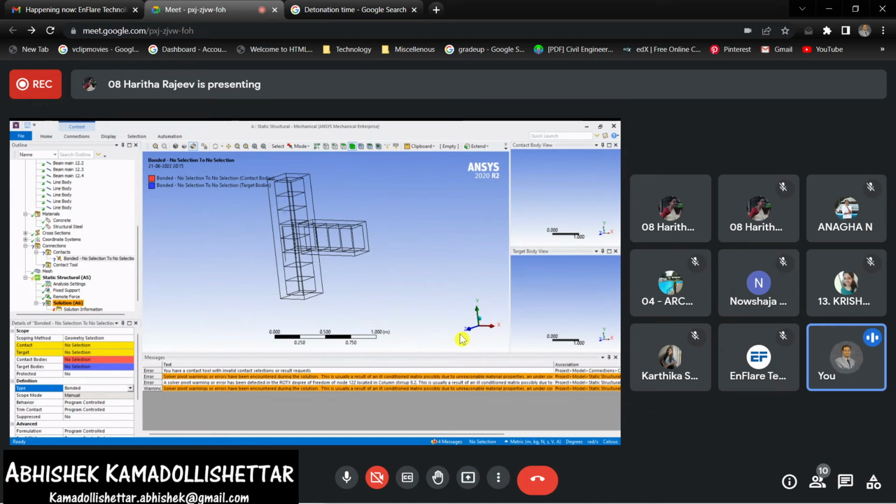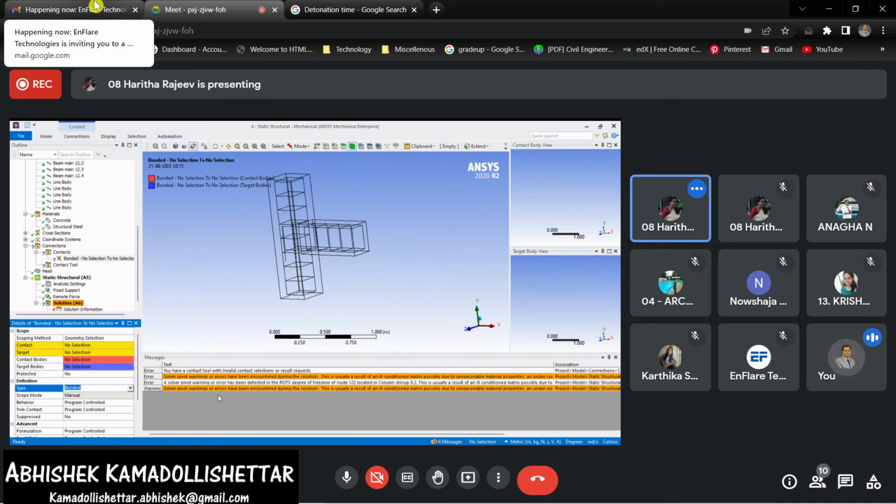When you're defining the reinforcement and concrete, you can make them frictional, but it will ask for the mu value there. So better you do it as bonded there also, because completely that will act as one member, right? Yes, sir. Fine. So that you have to do.